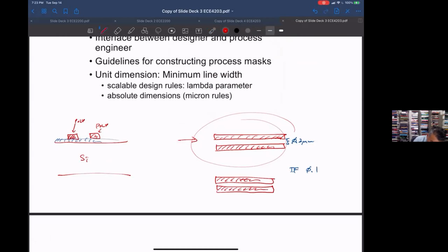But in effect, because my lithography equipment in this particular process is not good enough to resolve the space, to mask the space or create an opening in the space, depending what it is, I might actually get a short. It might look like a continuous polyline.